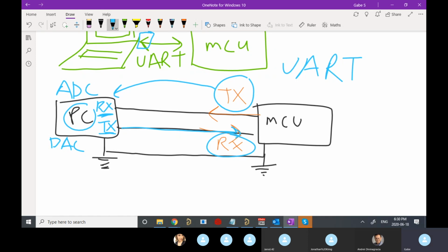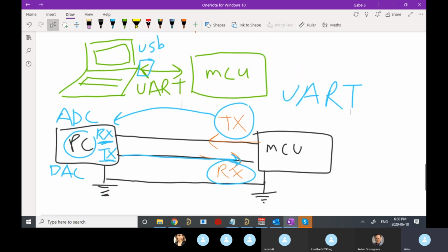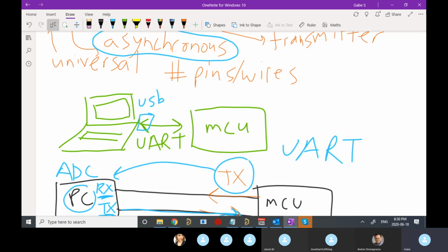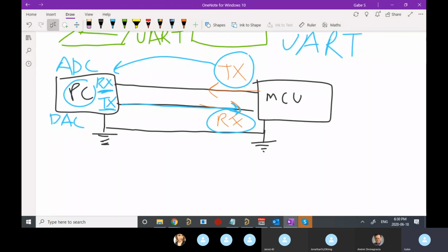Now, another really important thing about UART is that we mentioned it's asynchronous, right? We set that up here. And this is really one of the defining characteristics of UART versus other communications. All synchronous means is that it's the same sort of idea as if you and I started at one location together, we both had stopwatches, we synchronized them together, and then we go on our separate ways. And we will always have the same clock, will always have the same ground truth time to refer back to, because we're synchronizing them together. In UART, we're not. It's not a synchronous protocol. It is asynchronous.